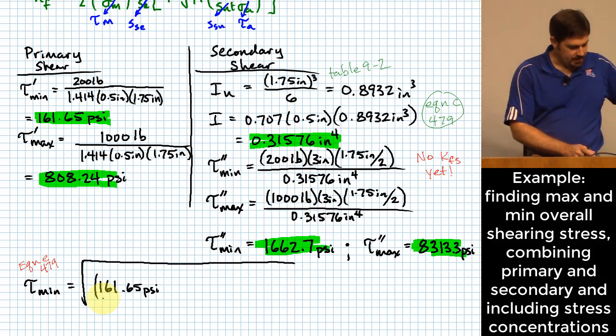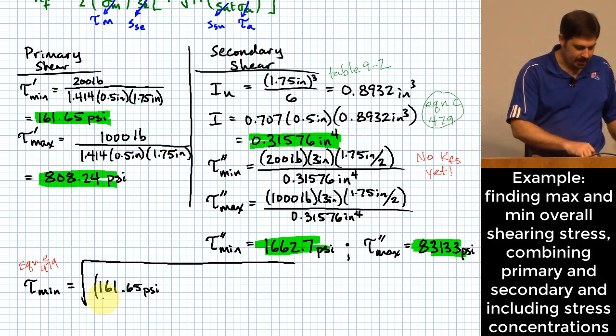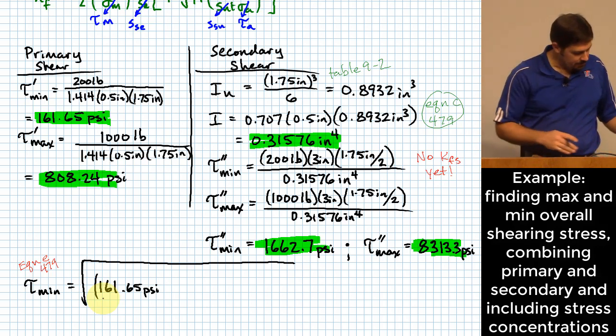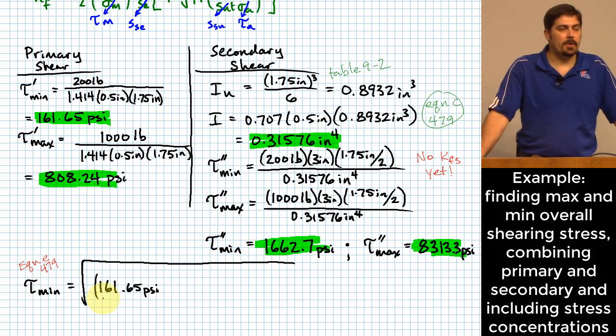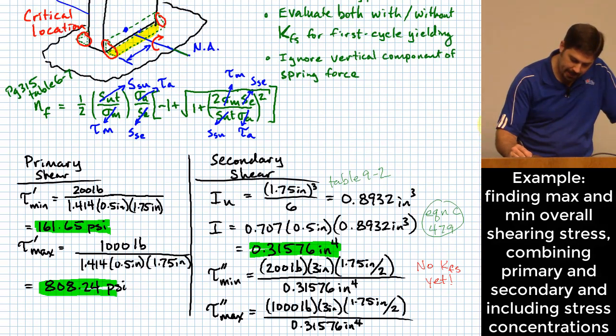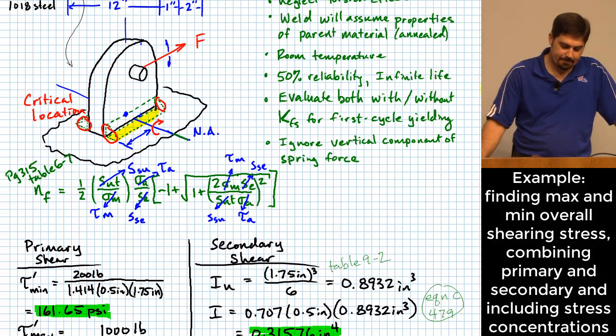Yeah, there is a table in the book that gives you some guidelines for what you might think about using for some stress concentration factors. And it gives it to you there by the name of the different kinds of welds. One of them says reinforced butt weld. One of them says toe of transverse fillet weld. One of them says end of parallel fillet weld. And the last one says T-butt joint with sharp corners. Which one of those do you think applies most appropriately for what we have in this case?